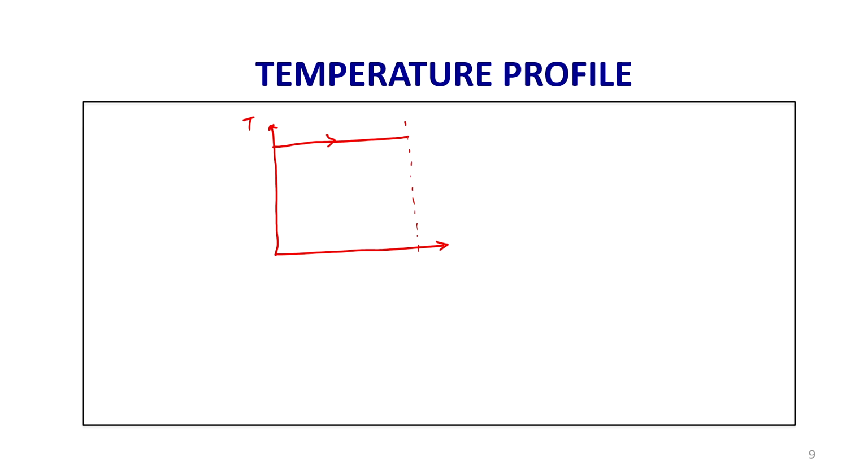Okay. So, the steam is coming, it is an isothermal process. So, this is condensation. Suppose we take the heat rejected during the condensation process, when the steam condenses from vapor into liquid, or a refrigerant vapor into refrigerant liquid. The condenser is cooled either by water or air. Whatever the medium we are using, its initial temperature will be less. After it has taken the heat, its final temperature will be more.